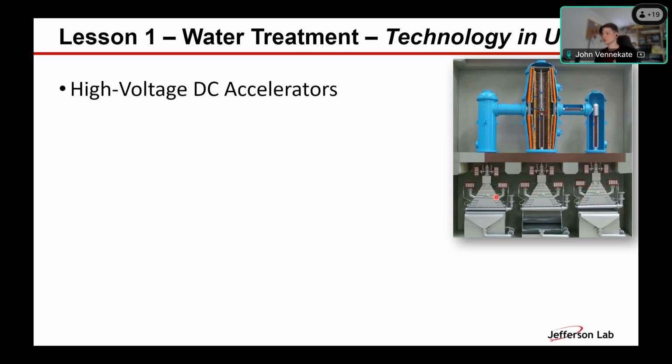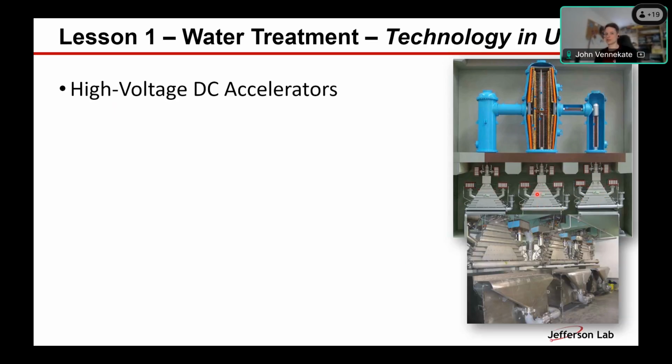And down here, you have multiple beam horns, and there's a constant stream of water being passed by these beam exit windows, where your electron beam is then introduced to the water, like I said, generating these highly reactive oxidants and reductants in the water, which then attack the contaminants from the textile industry that were brought into the water in the first place.